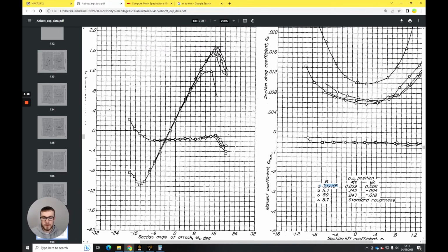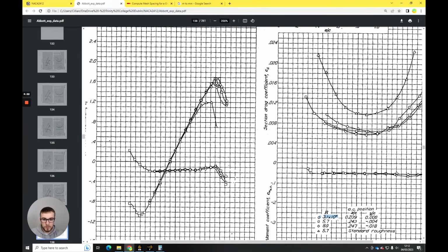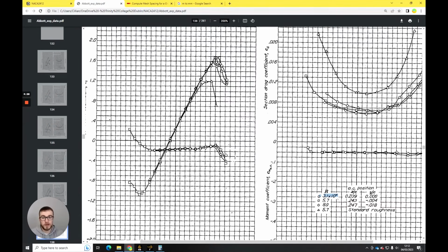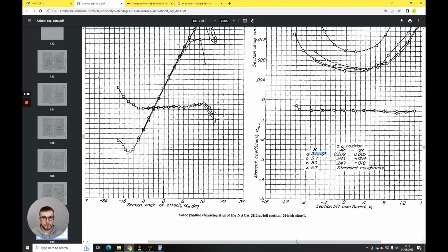The main value in CFD is that we'd expect, as we increase the angle of attack, to get a line similar to this with a similar slope. We should get similar values for our lift and drag, and our simulations should follow similar trends to our experiments, and then we know that our simulations are accurate in the sense that they're representative of the experiments.